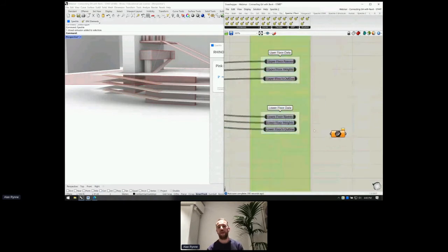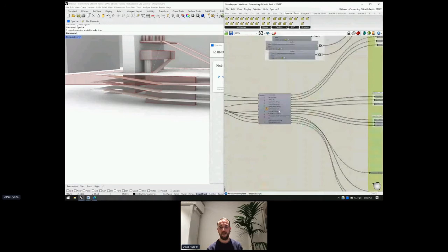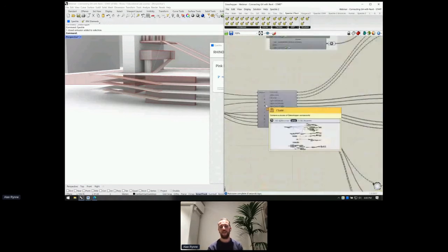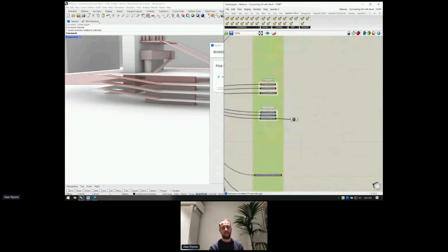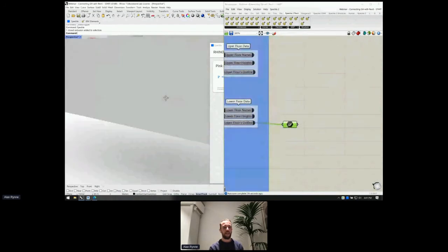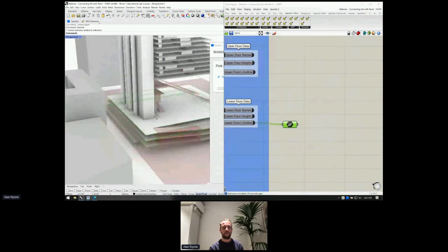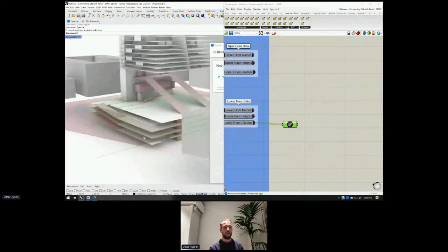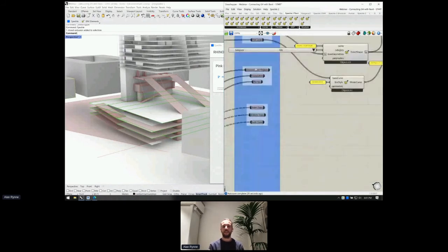This is a little bit of the black magic that I was talking about in Grasshopper that I hid on the cluster, on this massive cluster. It's basically getting the geometry and extracting the outline of each level, so with that, we can create the specific floor slabs. In this case, we're just getting, let's zoom that, there you go. In this case, we're just getting those basement level outline floors. So let's go step by step.